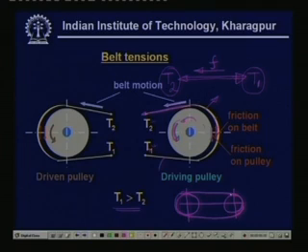So, we can see in the exaggerated figure, obviously the angle of wrap is decreasing, thereby the power transmission capacity will be decreasing. So, please keep in mind that whenever you are trying to design a belt drive, always keep the tight side onto the top surface, and I am extremely sorry, the tight side onto the lower side and the slack side onto the upper surface.